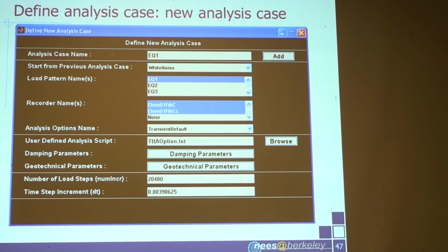you're sometimes losing that capability that you have in OpenSees when you do stuff in Tcl scripts, where you can control your whole analysis and do one time step. You analyze one time step, and then if it doesn't work out, you change your solution algorithm, you change your convergence test, and so on. Usually that's kind of hard to do through the graphical user interface.